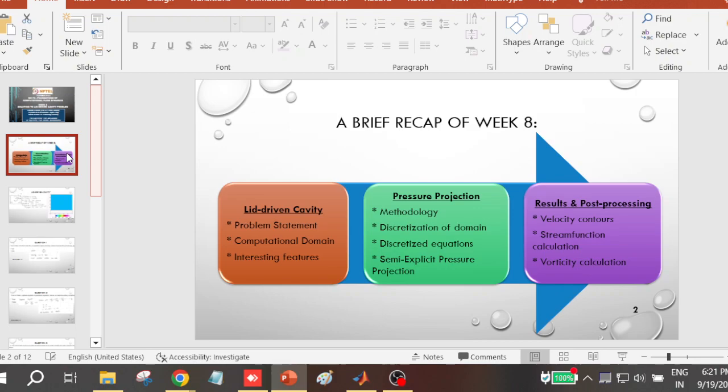For example, if you are doing just a flow over an airfoil, do you plot velocity and then just show these are my results? No. Nobody will understand. An engineer especially will not understand. So you need to show him or her the lift coefficient values and the drag coefficient values, and how they change with respect to the shape of the airfoil. Then there is some understanding. If you are doing flow over a cylinder for energy harvesting purposes, then you need to show the amount of power which you can generate from this much vibration. Similarly in many other aspects.